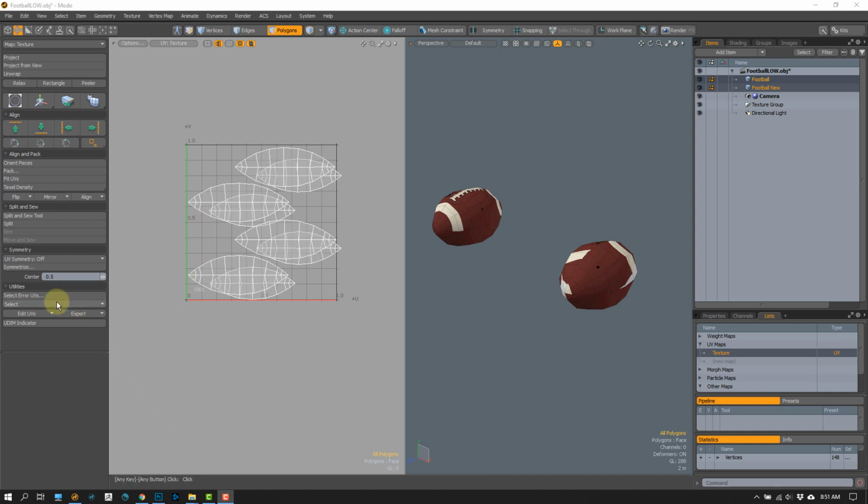It is actually hidden in this little menu right here. So I'm in Utilities, Edit UVs, and what we want is this little grayed out guy right here. It's called Transfer UV Position. So how we're going to use him is I kind of have to have a handful of criteria available for this to happen. So I need two meshes. The meshes need to have absolutely identical geometry. They can't have one polygon that's different. They both need to have an existing UV map. So again, these ones, the UV map is called texture for the unwrap.